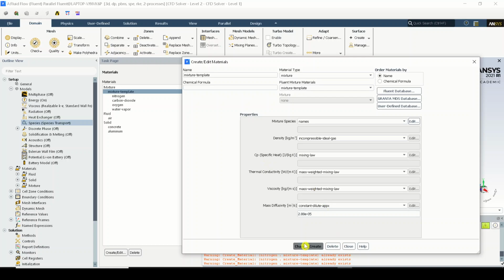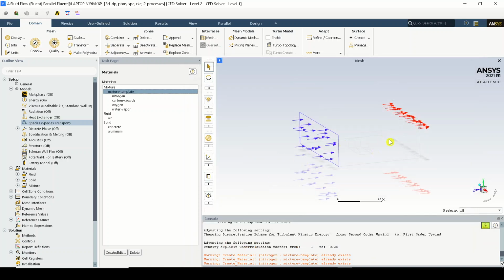You can just select different options and get some colorful results, but do they really predict, or try to replicate, a closer form of a realistic simulation, a realistic case? That is what is more crucial, right? So the selection of equations is very important when we solve any form of case. It can be an aerofoil, or this kind of case, or a hydrodynamic case, or any oil and gas case, or whatever case you're doing. The selection of equations is more important, right?